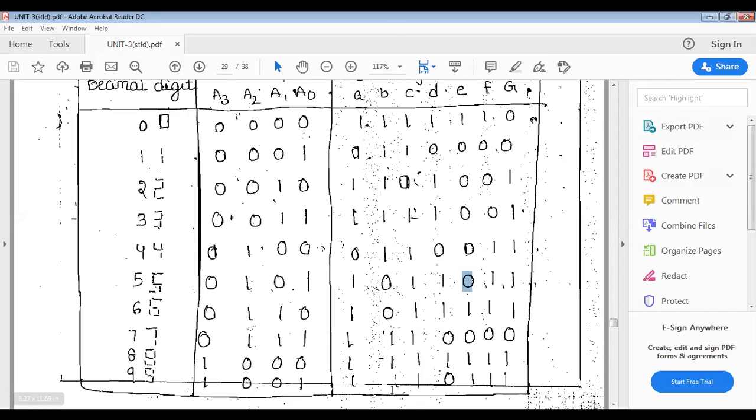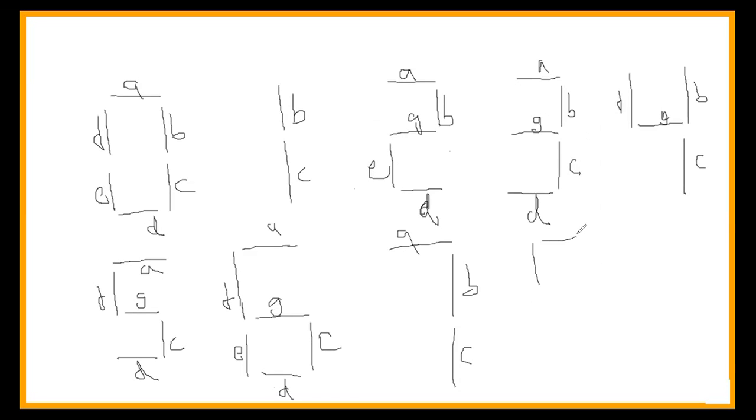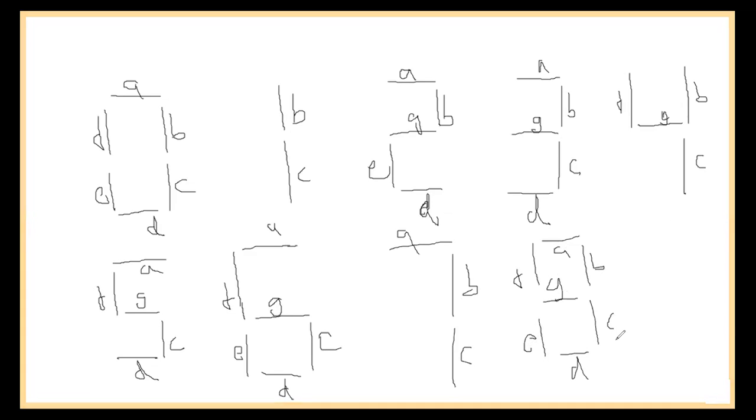And 8 means total it is on. How it looks like is 8. A is on, the B is on, the C is on, the D is on, and E is on, F is on, and the G is on. Okay, A, B, C, D, E, F, and the G. To display the 8, all LEDs from A to G are on.